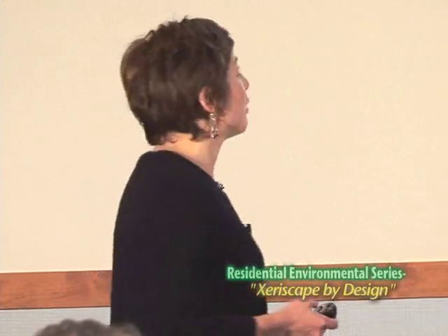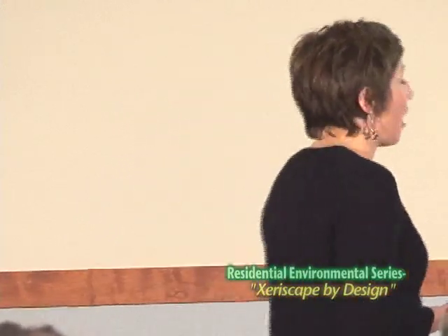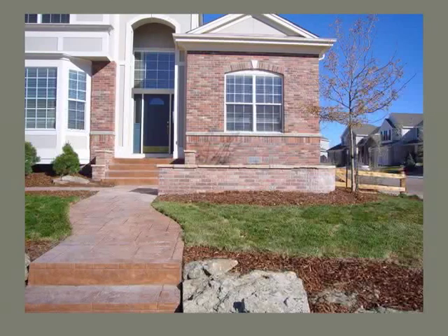So some of those paver and stone pictures I'm showing you are around 10 years old. I don't know if I'd be back to photograph that 10 years from now. So also, it is not permeable. So all that water is running off, getting in the urban drainage system, causing downstream flooding, not soaking into our ground, which we desperately need in Colorado. So that's the other thing I don't really like about it.